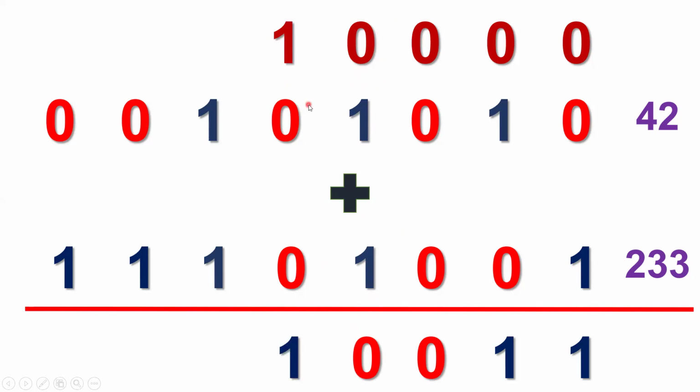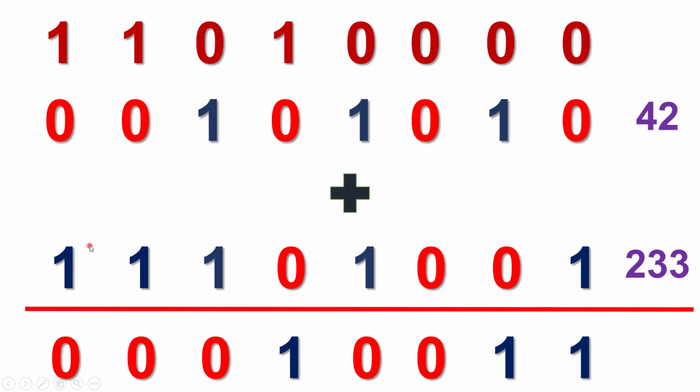And we see that now 1 plus 0 plus 0. The sum here is 1 and it generates no carry. Therefore, carry here is 0. And here 1 plus 1. Sum is 0 in binary, but it generates a carry that is 1. Again, 1 plus 1. Sum will be 0 and it generates a carry here. Then 1 plus 1. Again, the sum is 0 and now the carry gets generated, but it doesn't have any bits from number A or B, so it stays as it is.